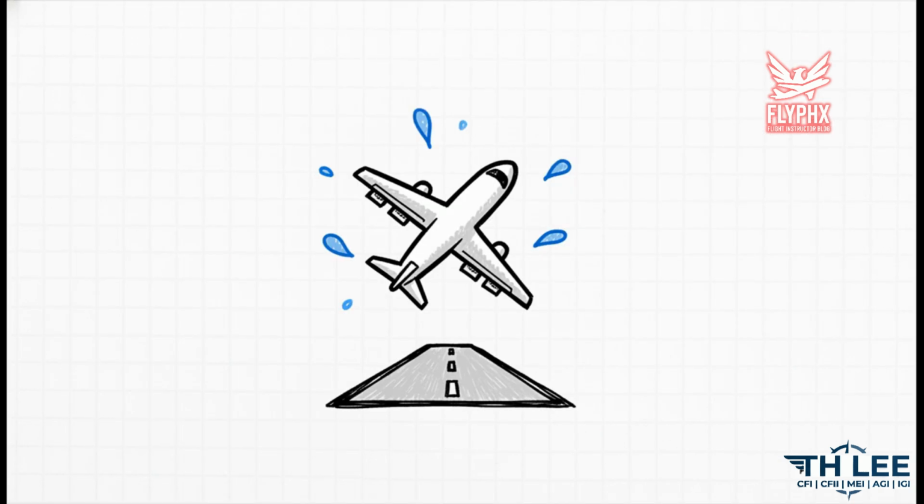The secret here is all about safety margins. Practicing with the flap set down at 25 degrees literally forces us to handle the worst-case condition on our performance charts. By mastering this specific setup, we're fully prepared and certified to take off safely on the absolute shortest, tightest runways out there. Basically, we train for the extremes so that your standard everyday flights feel like a breeze.